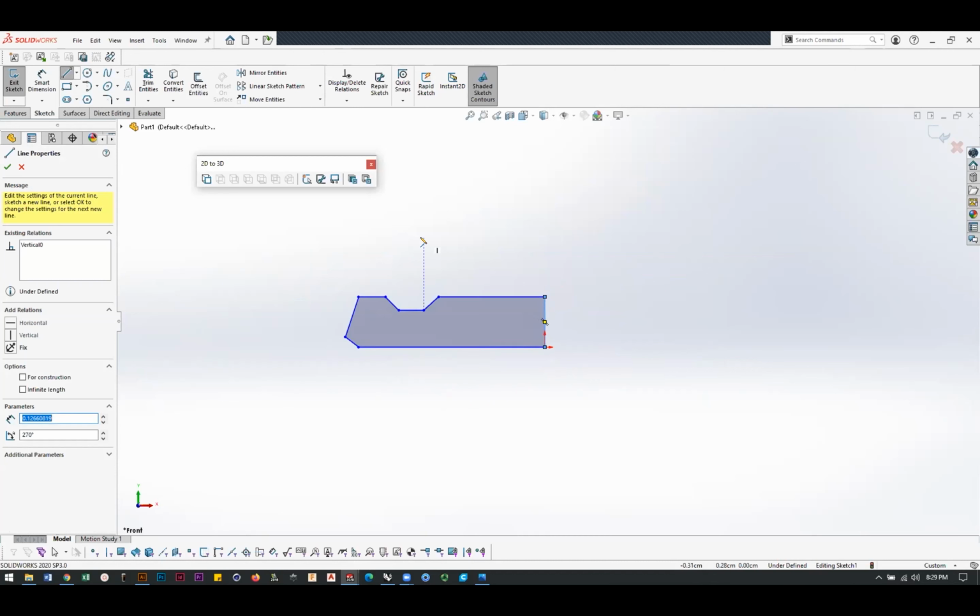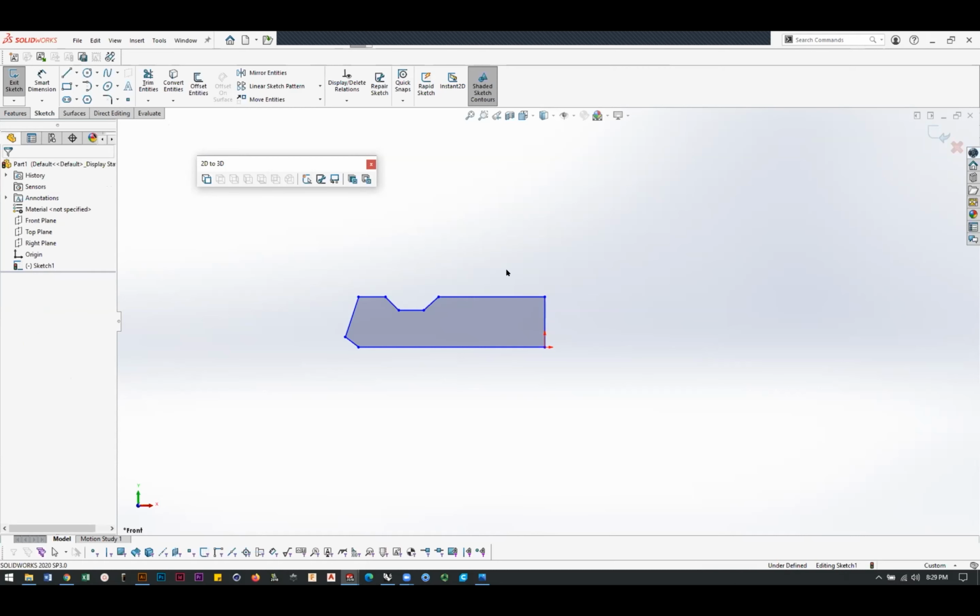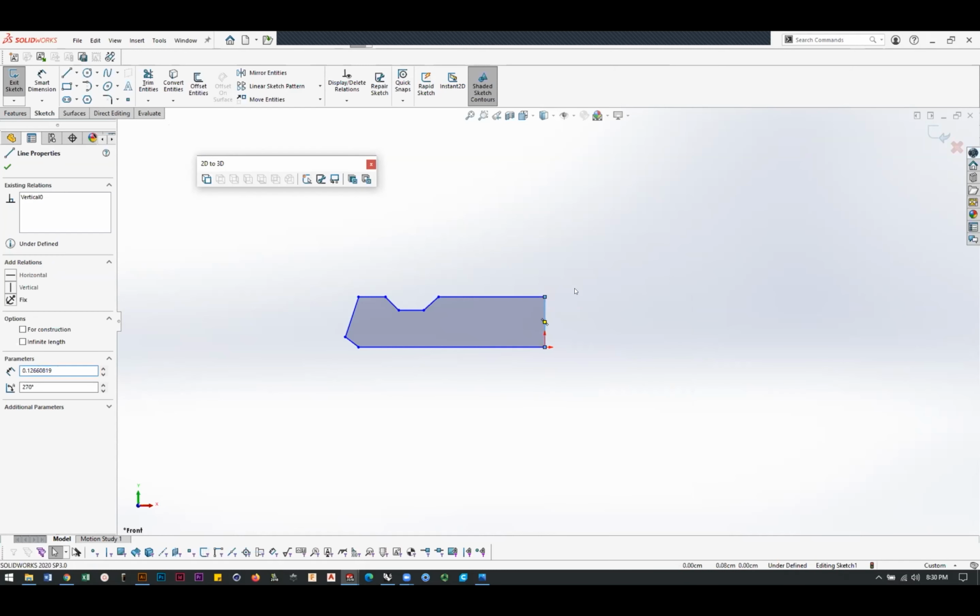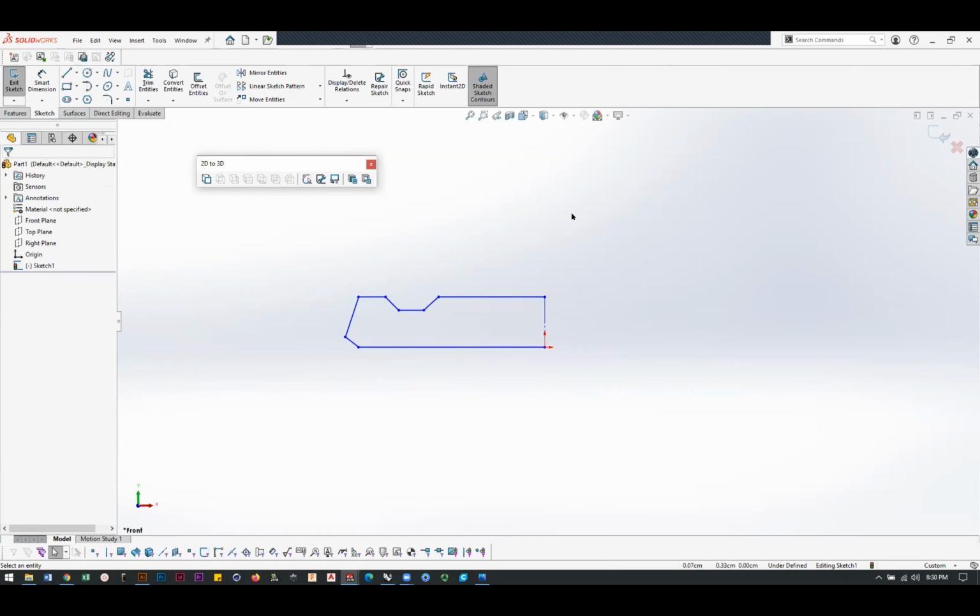So this is another good example of how line work is transferable between both programs, from Rhino to SolidWorks, but sometimes you're going to need to do a little massaging when you get into SolidWorks. For instance, the rules are a little different on doing a revolve in SolidWorks. SolidWorks likes to have a piece of construction geometry to spin around. Rhino doesn't really need that. So you do need to know the rules of how both programs operate when you're bringing sketches or line work from one program to the other and make adjustments as needed.